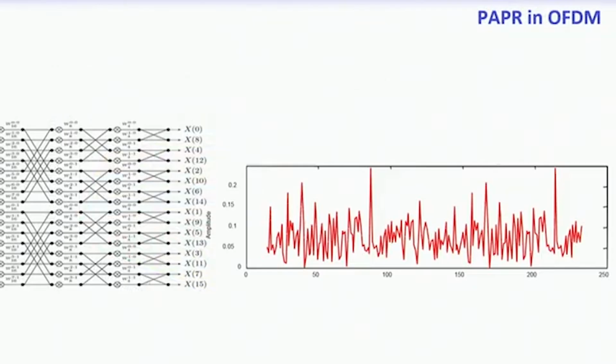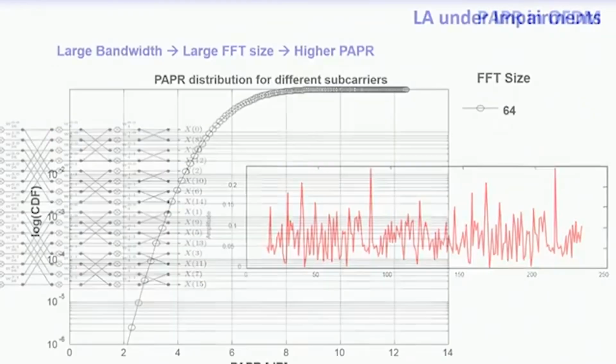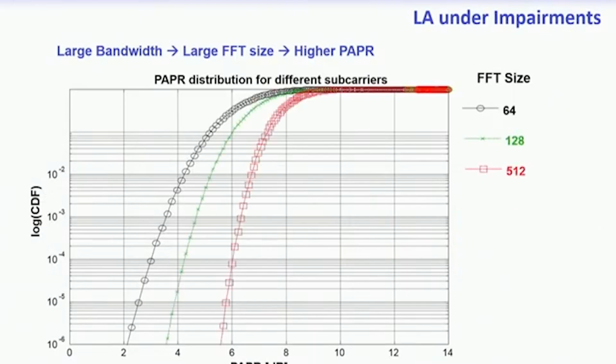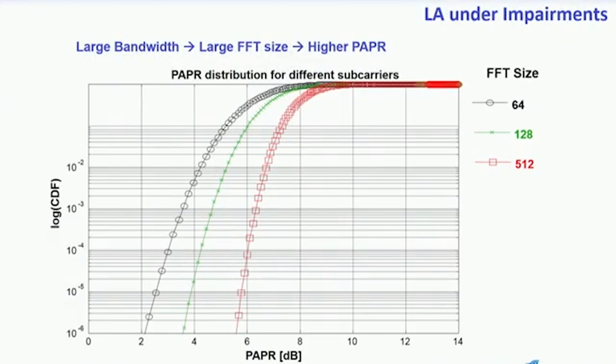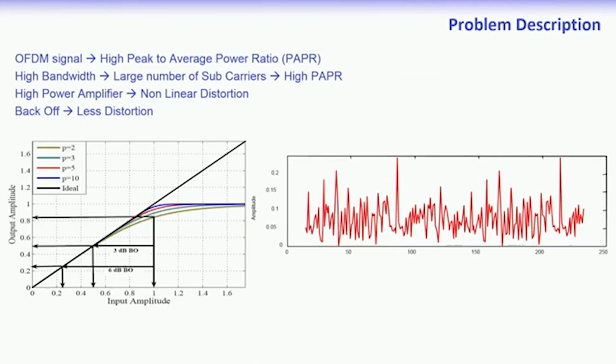In the previous lecture, we discussed how OFDM affects the peak to average power ratio, and how the probability of getting higher and higher peak to average power ratio increases with the subcarrier width. We have also described how it happens. These are some things one should note carefully, because these are the factors which ultimately affect the design of the system.